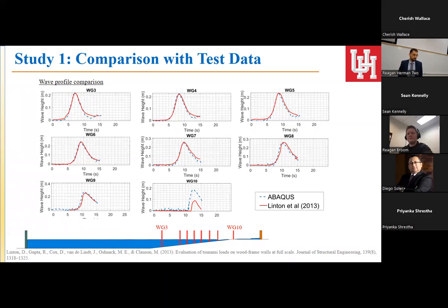Again, we must realize that the Navier-Stokes equations are being solved in incompressible form, which is totally fine, but our mesh was kind of coarse, so we couldn't capture all the scales. Also, the same problem has happened in other validation studies with this experiment. So we still have to figure out exactly why this happens.